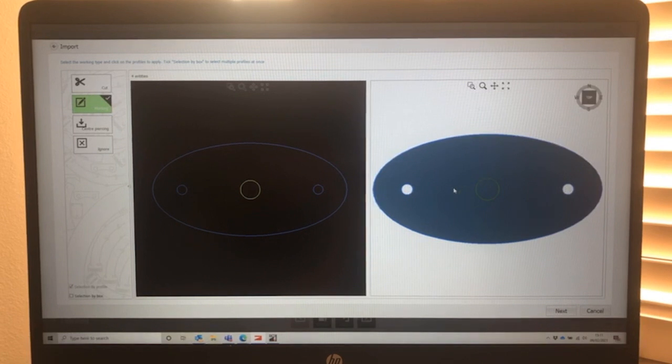What it's going to do is etch that circle onto here using the marker tool, and then cut the rest of the components. As standard, it will always set it to cut. After that, you get the option to look at changing this. The other alternative to this is the center pierce tool, which is the red one.